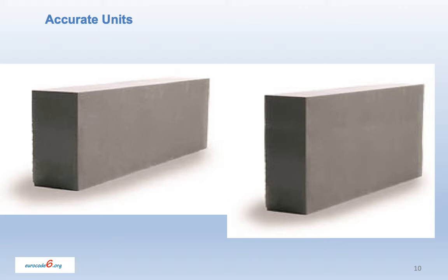The masonry unit standards all provide detailed information which the manufacturer will provide in the declaration of performance for a particular masonry unit. The declaration gives key information including dimensions, strength and configuration. In addition, it is possible to specify tighter dimensional tolerances when units are required for applications such as thin joint masonry.